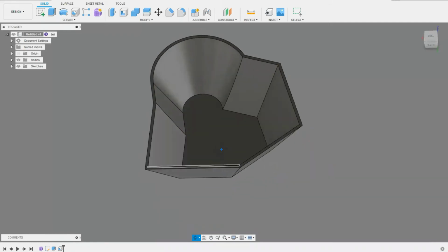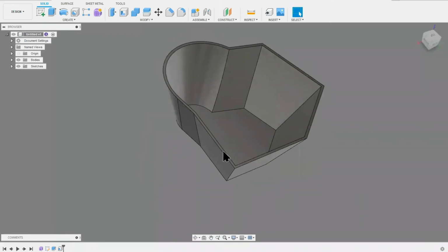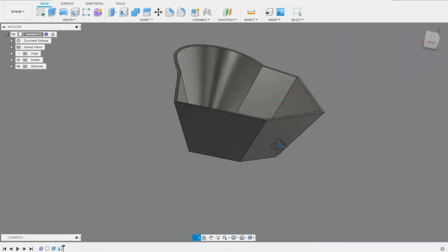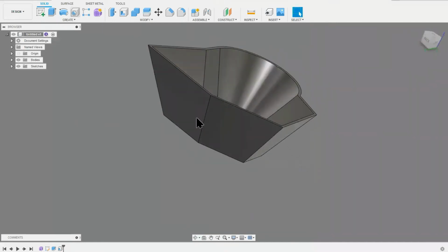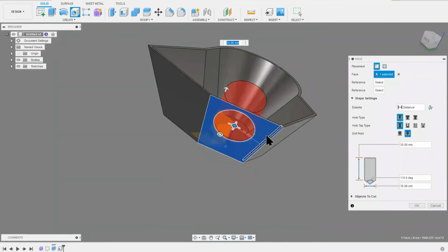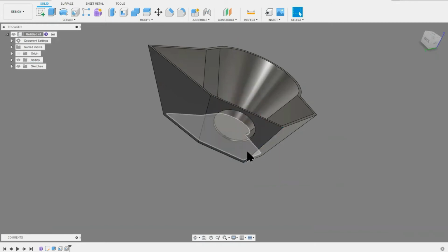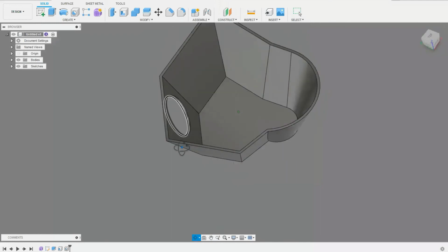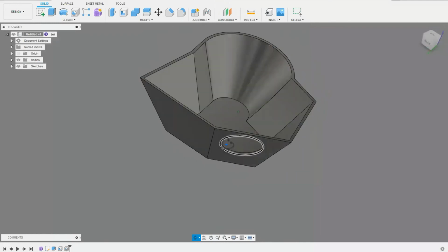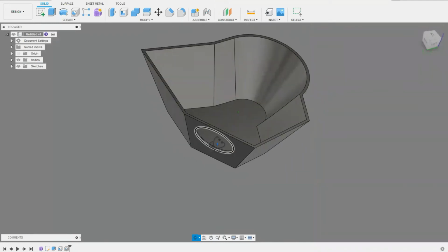Aspects of solid modeling are for things like placing holes. If I choose to place a hole in this face and tell Inventor that I want to place a hole through there, as you can see, we can model that solid feature into the space.